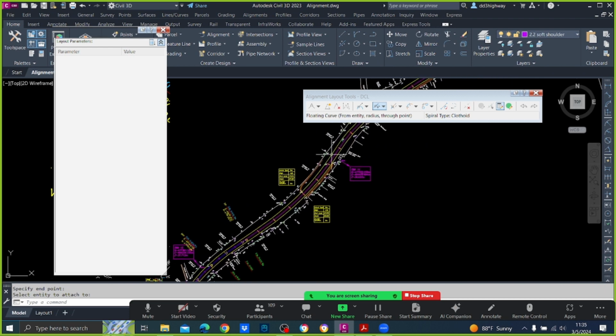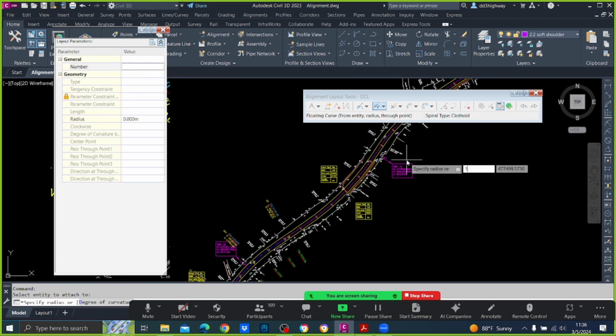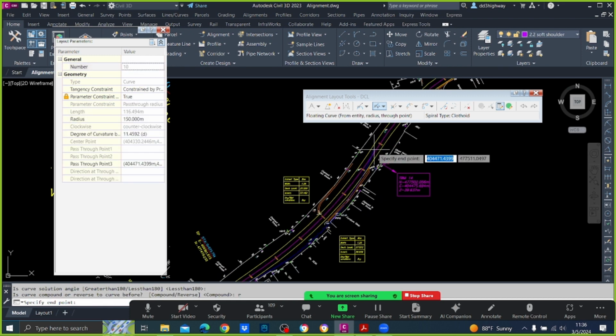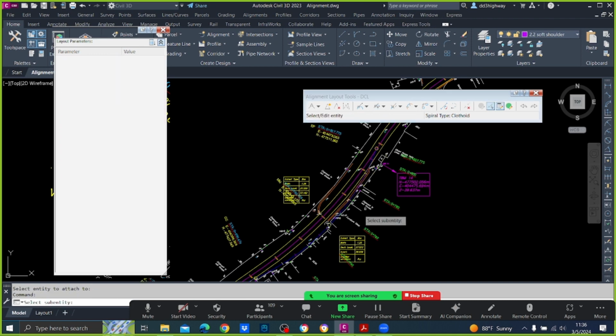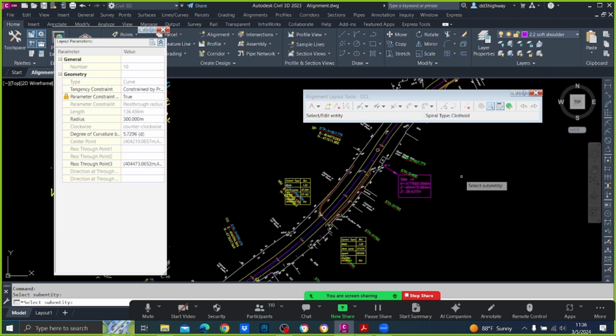And here you are having again another curve. So you can try using floating curve. Say we'll say 150. So again reverse. So it is not 150. Can you see? It is a larger curve. So maybe go for, say, 250 or 300. 300 seems okay.